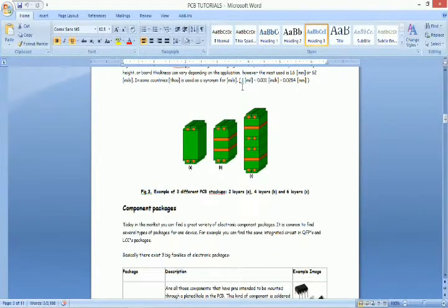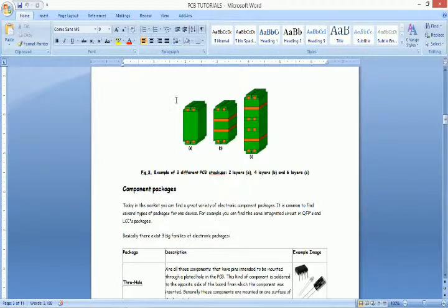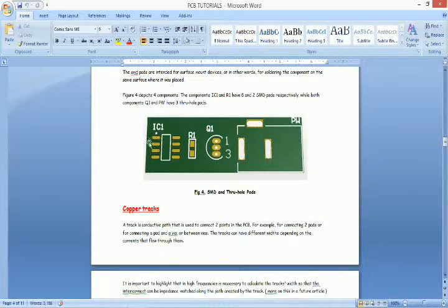Also, one thing you want to consider is that while you are making a hobby circuit, most probably you are making a single layer PCB. There are also multi-layer PCBs which can be designed using Proteus. So you must know the basic measurement unit used in PCB design. PCB design in Proteus is usually done in the unit of thou. One thou is 1/1000 of an inch, that means 0.001 inch. This is also called mils. You can also set the basic settings to the millimeter range. I explained pads already. You can see examples of pads here, oval shape and other shaped pads.